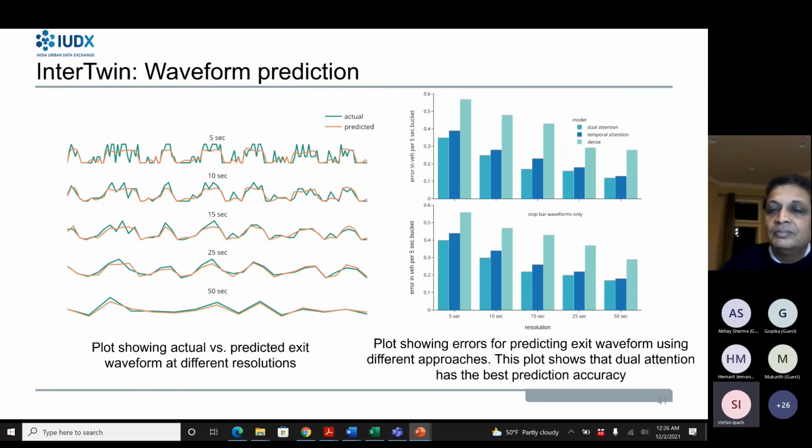He's asking, in a real-time digital twin using AI, which model parameters are updating, and whether the gap is dynamic or fixed configured. Our goal is to build a twin which will have both the intersection parameters and the driving behavior parameters included. We want to use the data coming in from the real world to impute the behavior of the driver, in terms of gap analysis, and how many people speed on the intersection or between intersections, because none of that data is observable directly. Those are all latent variables in most real world situations.